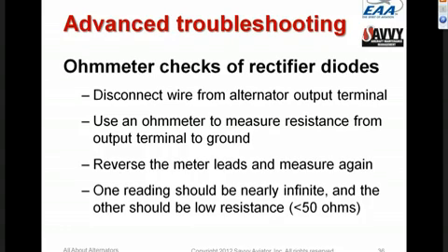I'll probably skip over this stuff. It gets a little bit technical, but we can use an ohmmeter to check the rectifier diodes and to make sure that they're conducting in one direction, not in the other direction.